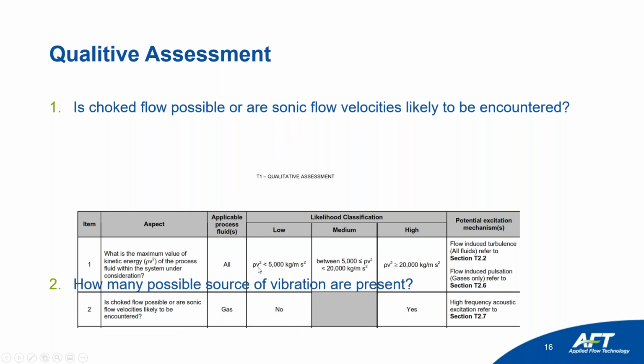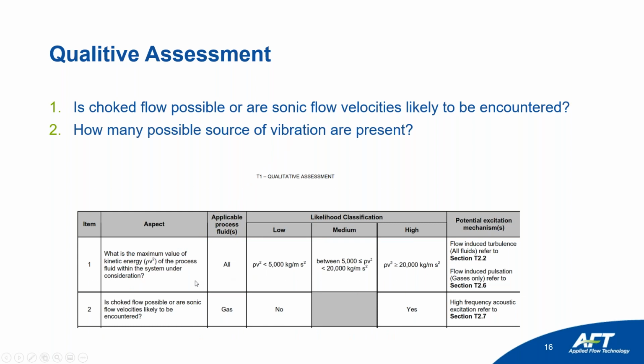Another question that has to be answered is how many possible sources of vibration are present. And a third question is how many discontinuities are present. As we said, discontinuities are the weak points to be analyzed because they have a stress intensification factor that makes them a critical point. So let's bring up the program, the model.